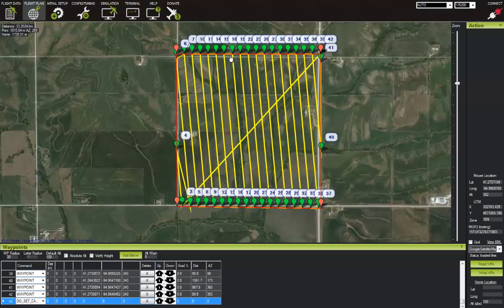As each waypoint is met, a camera trigger response will be automatically given to the onboard camera while taking into consideration the programmed amount of overlap you specified during flight programming. Again, depending on how the wind is blowing on a particular day, the time needed to get to each pre-programmed waypoint will vary, with individual flight time not being a factor for triggering the onboard camera at the necessary points of reference. The system is designed this way so that crosswinds will not bump the UAV off of its required path, and so that all of the waypoints can be met regardless of the wind speed or direction.